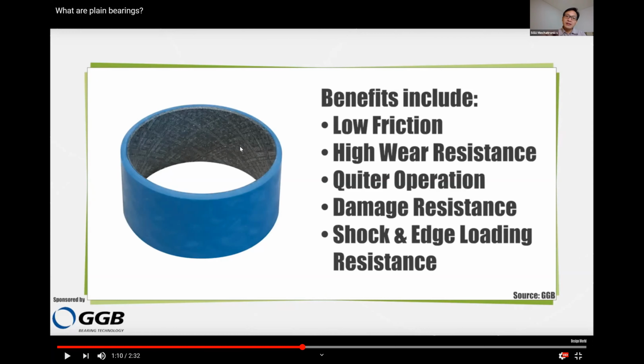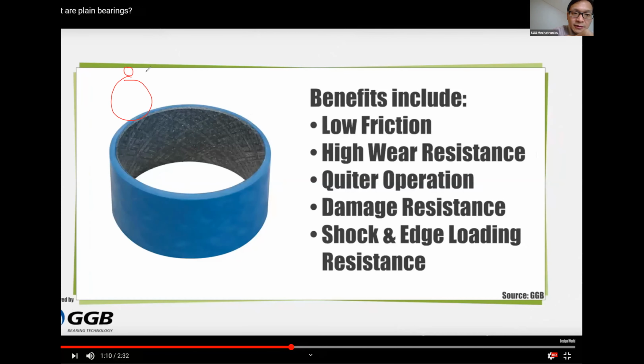Okay, you can imagine the ball bearings, I could say just bearings, these rolling elements, they create a point load. Okay, so the load at that point is pretty big. But these guys spread the load over a bigger area. In fact, that's one of the things that we will do in the calculation, this average pressure.